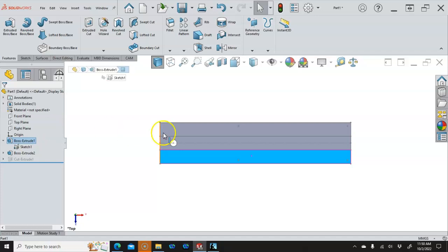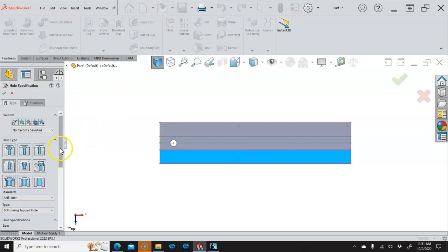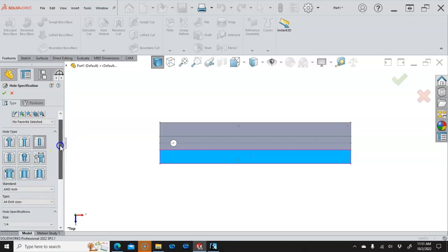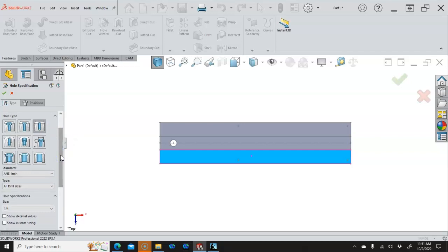And we have 5 millimeter holes, 10 millimeters deep. So this is where we can start to use the hole wizard. If I just drew the 5 millimeter circles, I could extrude them 10 deep, but we'd also want to utilize some of the drill geometry, or if this is a drill and ream type situation where we want this to be close, because usually the pins are going to be a purchased part, so those are whatever size the tolerance of the manufacturer provides.